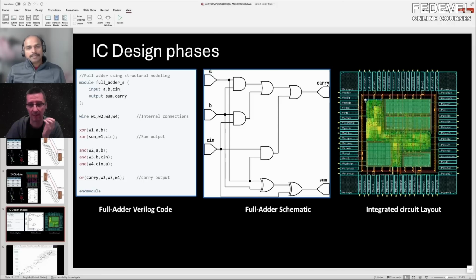What I found the biggest problem is that routing boards is also about placement. When I do placement, I always think about how I'm going to route the specific components, but the autorouter doesn't know. You can set up some rules and tell it, this has to be this distance or something. But the autorouter starts routing somewhere, and then it will find out it's not possible to connect it based on your specification.